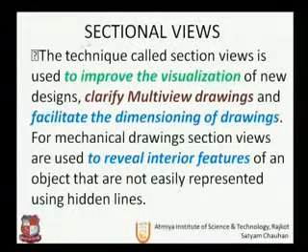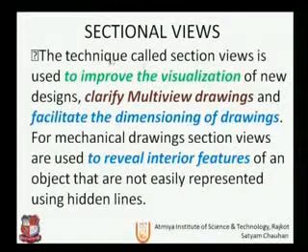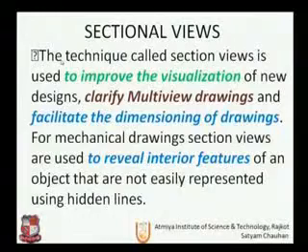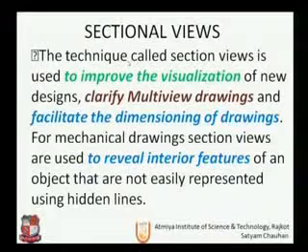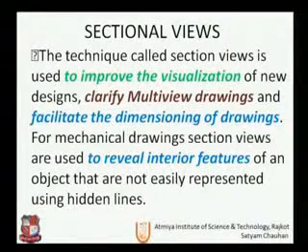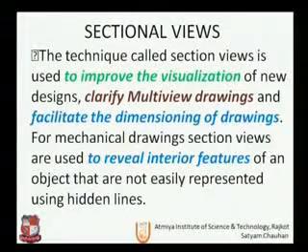Sectional views, what does it mean, and what is the requirement for the use of sections in the drawing? It is very common in mechanical objects that a technique called section views is used, first, to improve the visualization of the new design; second, it clarifies the multiple view drawings; and third, to facilitate the dimensioning of the drawings.